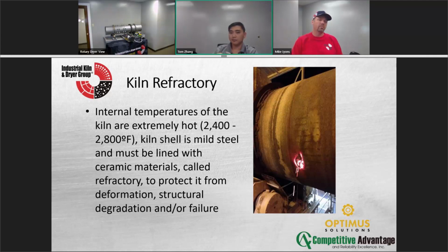If you have bad refractory, that typically causes mechanical problems. That's where we go back and you should do an ovality measurement. We actually are going to have a small session on ovality at some point to discuss details on that. But ovality is a very good check. You can do it running, and that is normally for refractory.